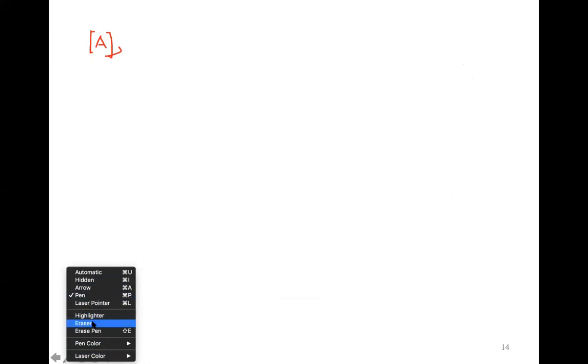What we are going to see is that the attitude matrix can be represented in different ways. The main representation is the direction cosine. We know that the attitude matrix is given by 9 different elements, but we also know that those elements are not independent.